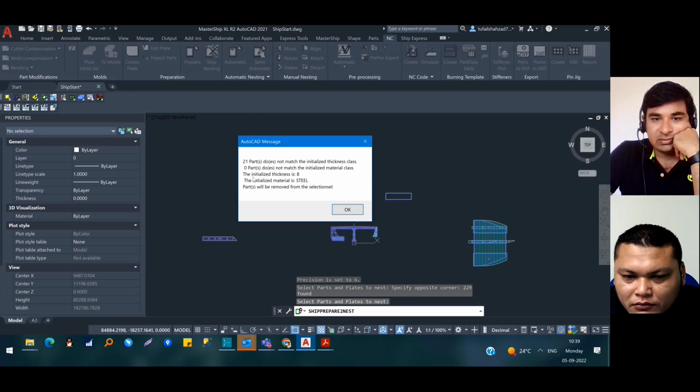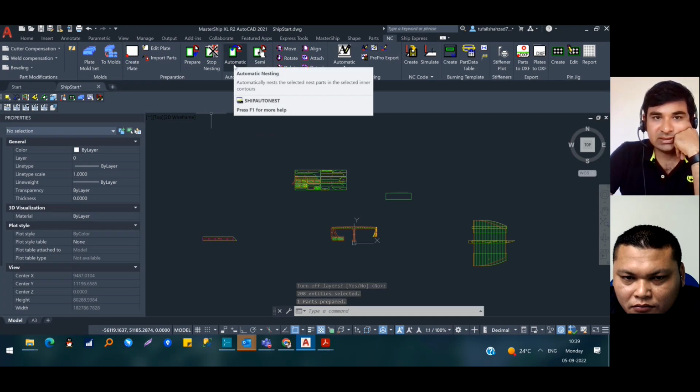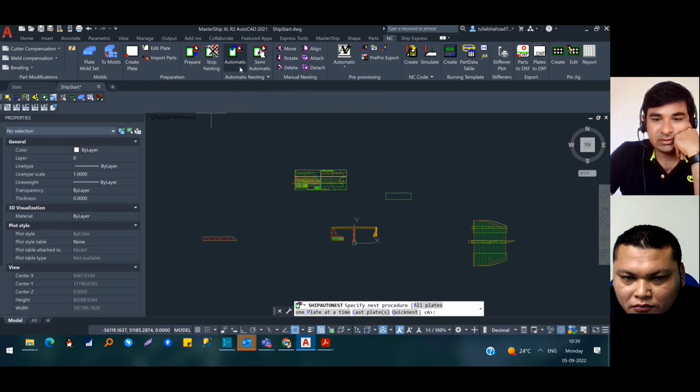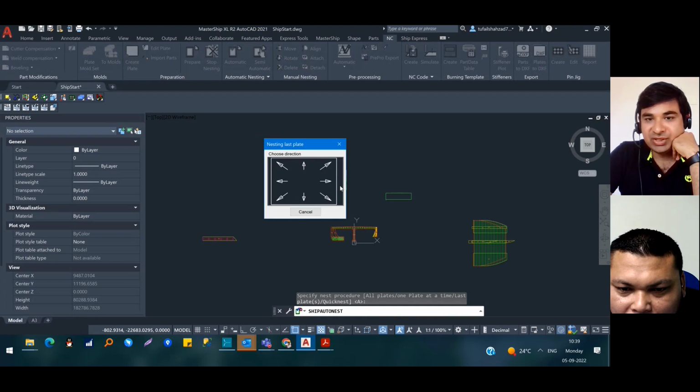And then I will say prepared, standard procedure, everything. That's okay. And now I'm going to call it automatic nesting. And then I'm going to say last plate. And then it asks me which direction you want to start with. So maybe it depends on you. You want to fill from here to here, from here to here, up and down. So we usually say from here.